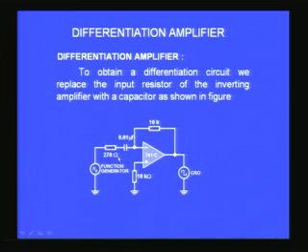So this is my differentiating circuit. Why I have added this 270 ohms at the input is precisely the reason that I already mentioned to you: in a differentiating circuit, the output gain is going to be a function of frequency. Therefore higher frequency components from so many other noise sources can be preferentially amplified, and therefore the output will become buried in noise.